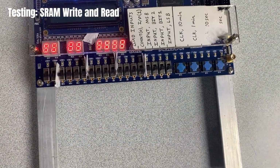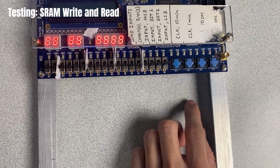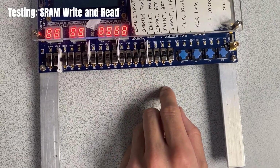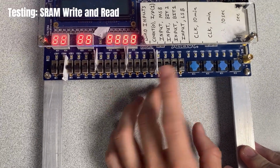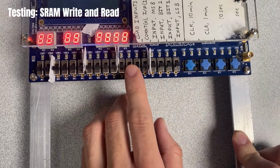We're going to be reading and writing to and from the SRAM using registers. So these 4 switches are the address of the RAM, and these 4 switches are the data. I've got the registers in green over here. And when you write to the RAM, it takes it from the register. So I'll show you what I mean.